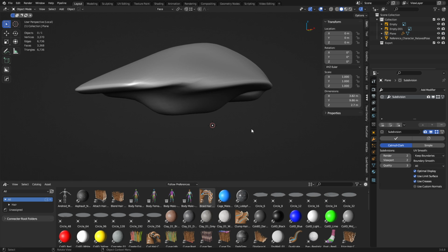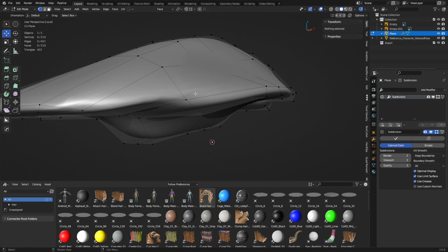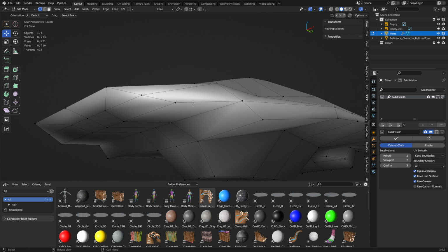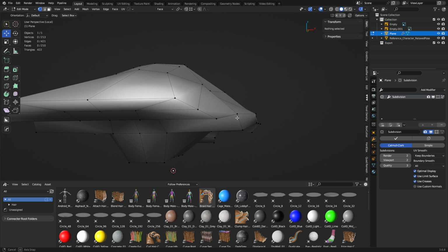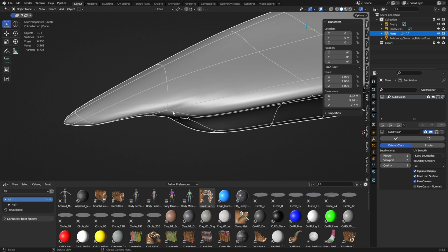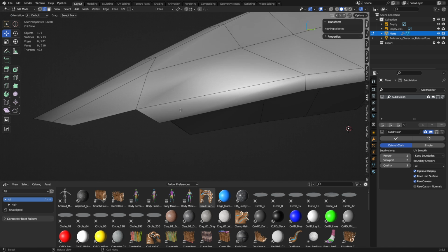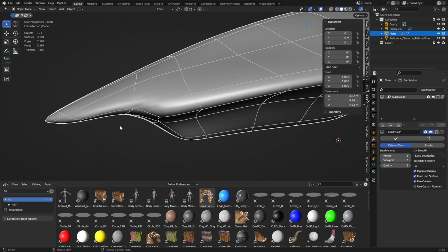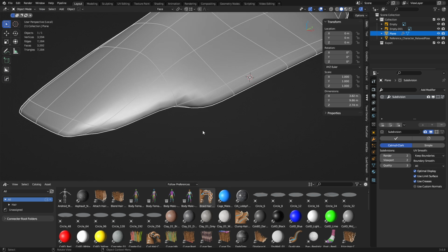So all in all, we see some topology issues here, where things just maybe aren't working the best they could, or they're not quite right. That's normal. You'll have to go through and fix little areas like that potentially. Like this pole here, this E-pole does not seem to work too well. We could add a holding edge perhaps. It might kill off some of the curvature.